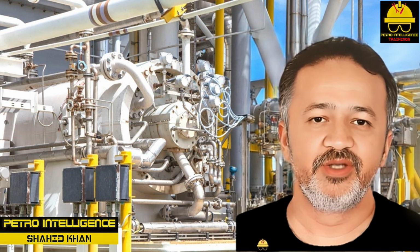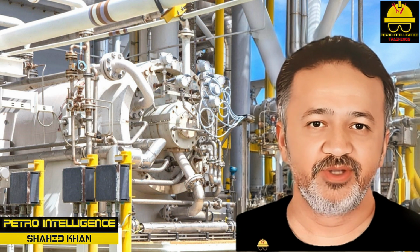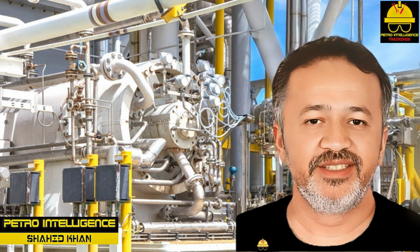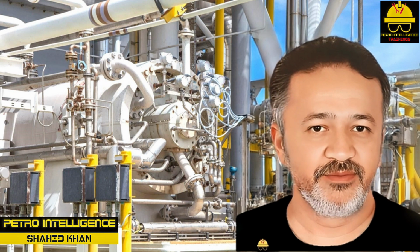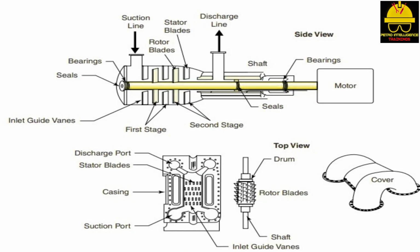Axial flow compressors. In the industrial environment, axial compressors are the compressor of choice for jobs where the highest flows and pressures are required. Unlike centrifugal compressors, axial compressors do not use centrifugal force to increase gas velocity. An axial flow compressor is composed of a rotor that has rows of fan-like blades, as shown in the picture. Airflow is moved axially along the shaft.